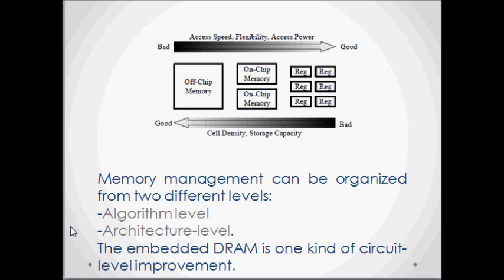The on-chip memory, usually implemented by SRAM, provides faster access and less power consumption than the off-chip memory, but the memory cell size is much larger. Registers can be faster than on-chip memory and provide more flexible data storage. However, the size of a register is the largest. Registers are more suitable for the implementation of smaller size buffers.